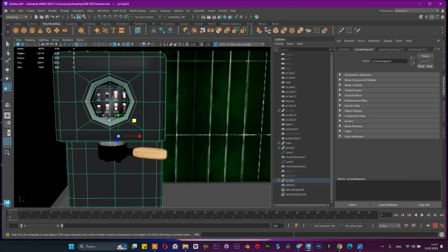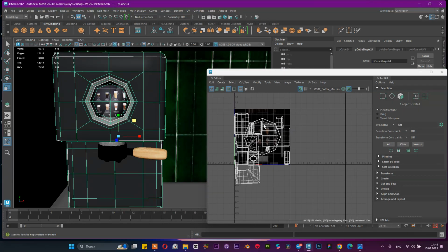With the help of selecting faces and applying material on these faces, we can easily make some textures and add some details. But this process is only for rendering. When you are creating models for games, you should keep every UV in one UV editor square, and you should use Photoshop to collect all of these pieces into one texture.